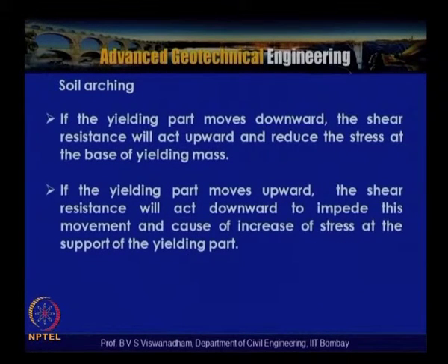If the yielding part moves downward, that means the soil above the conduit, the shear resistance will act upward and reduce the stress at the base of the yielding mass.